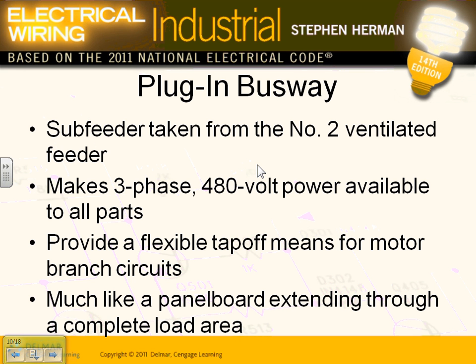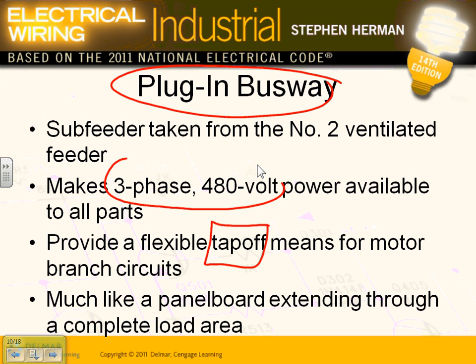Okay, so the second one is the plug-in busways that we talked about, guys. The most important thing is the takeoffs or the tab-offs that you can take out of these to feed equipment. Three-phase, almost always. At a system like this, guys, you're looking at three-phase 208 or three-phase 480. Almost always.